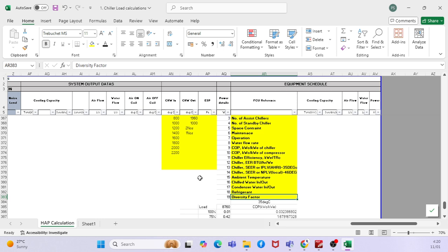When you enter the data, you can go either way as well, but most of the time, even for residential, you would still take the 100% load, but you would maybe add a diversity after carefully analyzing the worst case scenario based on experience, and then bring in your diversified chiller values.